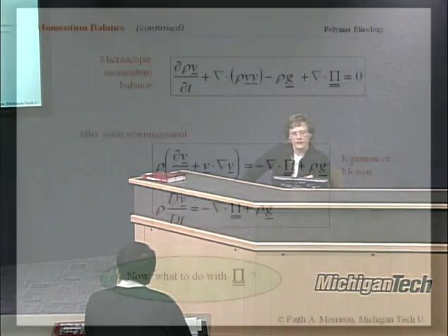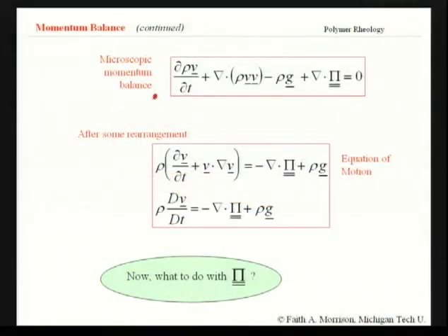We have spent a fair bit of time deriving the Navier-Stokes equations. And the Navier-Stokes equation is the microscopic momentum balance. So we ended up with this version, which has our friend, the stress tensor in it. The formal name of this tensor is the total stress tensor. And I don't say that because I actually don't deal with pi very much. I mostly, after today probably, will only be talking about tau, the extra stress tensor, which I'll just call the stress tensor.